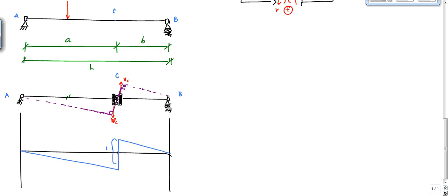It can't just start automatically elongating right here. So this is really this 90 degrees. And this slope right here has to be the same as this slope right here. And what that means is that if this total distance right here is 1, and I extend this line out all the way right here, relative to the original beam, this distance right here is 1, and the slope of this line right here is 1 over L. Okay, does that make sense?